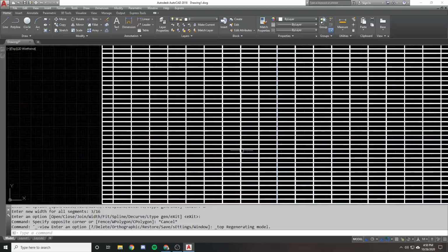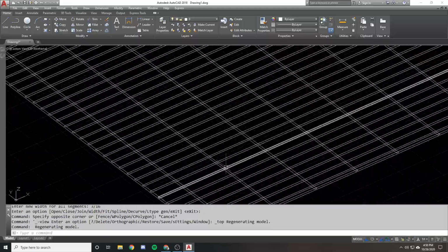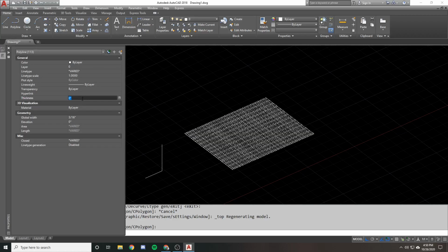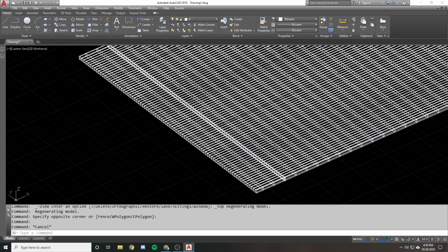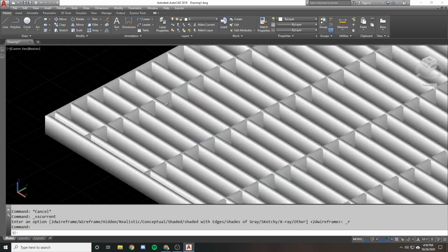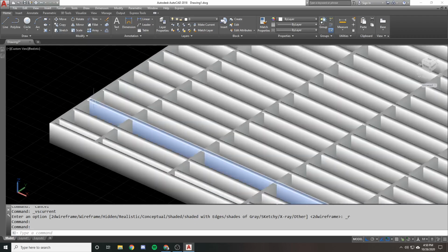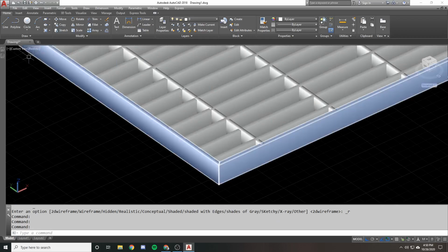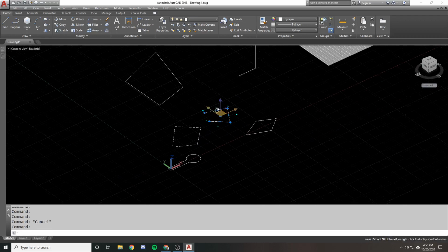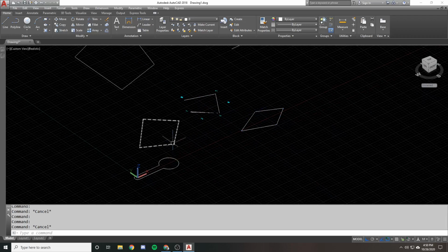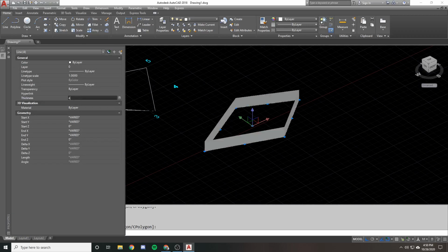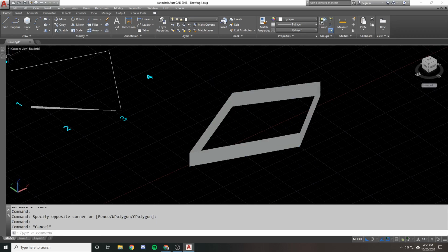On top, they look solid, but as soon as you go to an angle, they turn into what looks like a hollow line type. And then from this point, I can actually give them a thickness, like I would any other line, of like an inch. And so now I've got what looks to be a somewhat realistic looking grating. These are just polylines that I've given a thickness and raised an inch using the thickness. A line thickness is basically taking a line, like any line, like this, and just raising it whatever you need. 4 inches. This becomes a line that's 4 inches tall.